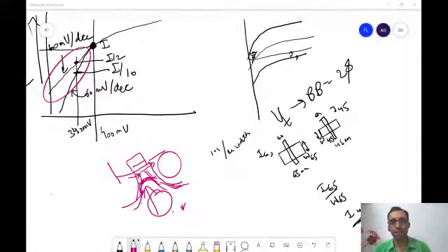Right? Yes, sir. So I understand why that happens, but is it that even in normal long channel device operation, no matter what we are doing, no matter how much current we are having, if there is a pinch off, then beyond pinch off, there is velocity saturation. Is that true? No, you cannot definitely say that. There may not be velocity saturation just after pinch off also. It depends on the device dimensions. Okay, sir. It depends on the electric field that we're talking about. Okay, sir.